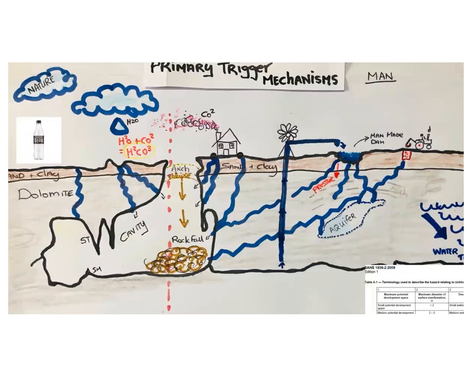That is, the more man's activity happens, the more draw off, the more open, the more surface interaction, for example digging of drains and excavation, the higher the rate, or the potential, of these dolines falling, especially if you're in an area that has a high categorization, D2 and D3. Saying that, let's have a look at a few things.